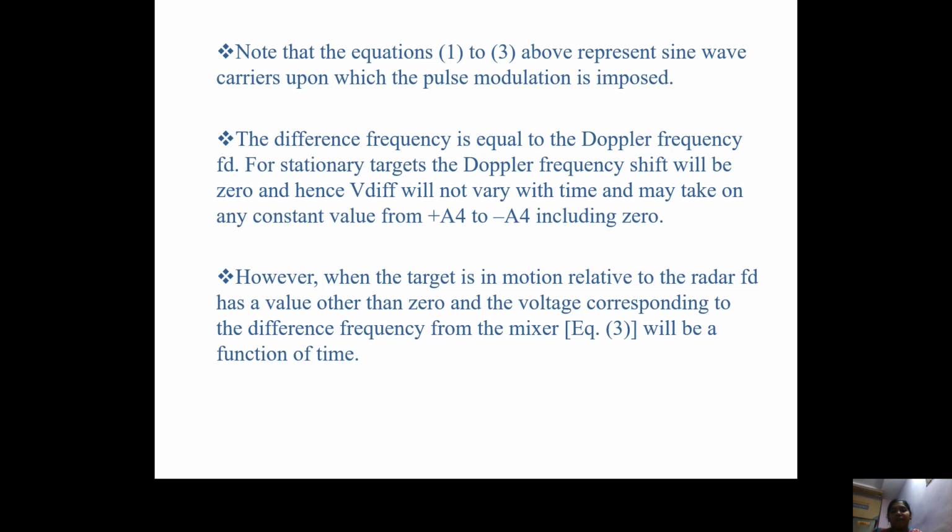However, when the target is in motion relative to the radar, FD has a value other than 0. So when the target is moving, obviously it undergoes frequency shift, which is nothing but the Doppler frequency shift. That is why it has a non-zero value, and it has its own corresponding voltage from the mixer. So it is always a function of time.